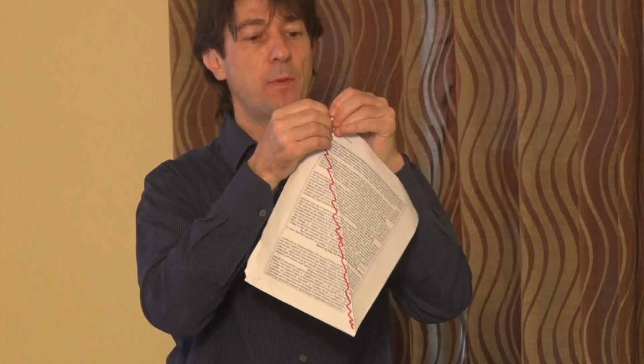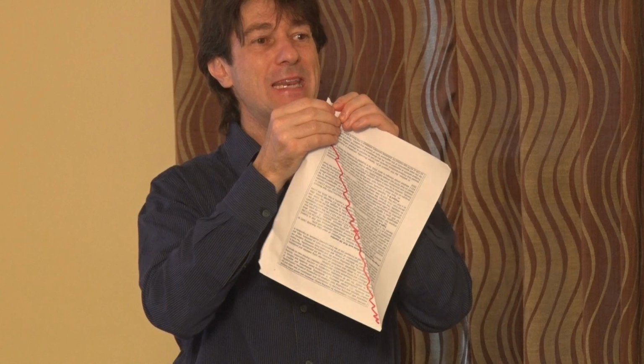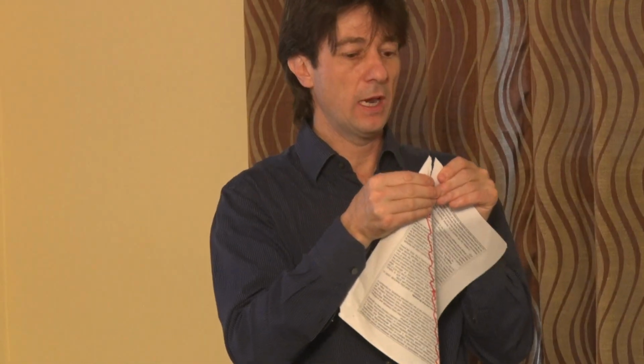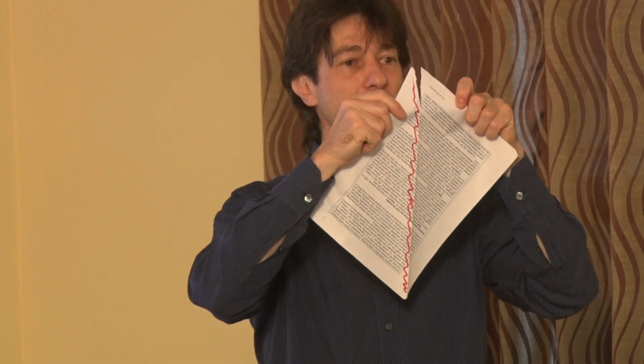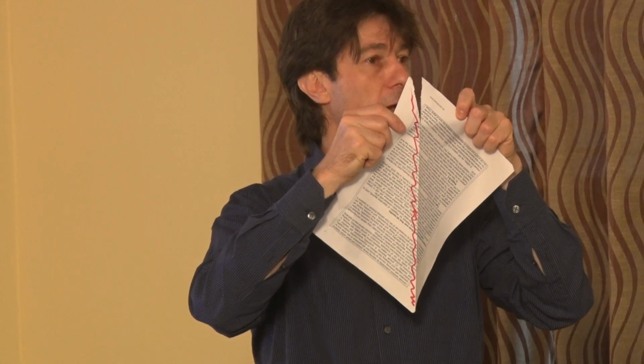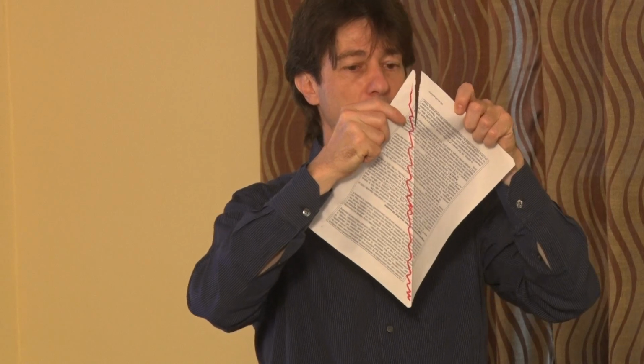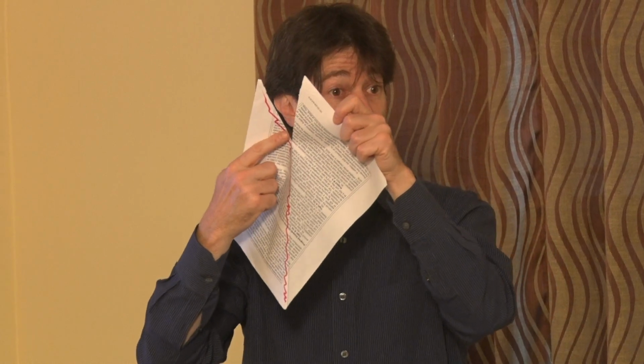At some point, what is happening is actually I will apply enough stress, and that stress will result in a displacement that will be localized at that cohesive element. And what is happening is basically I'm pulling the two apart and I'm breaking. So now you can see that part of my system is broken and part is still connected. And this point where the fracture is propagating, now here, is really where you have the transition from a continuum to a discontinuum. So there are several ways that this fracture mechanics has been implemented.